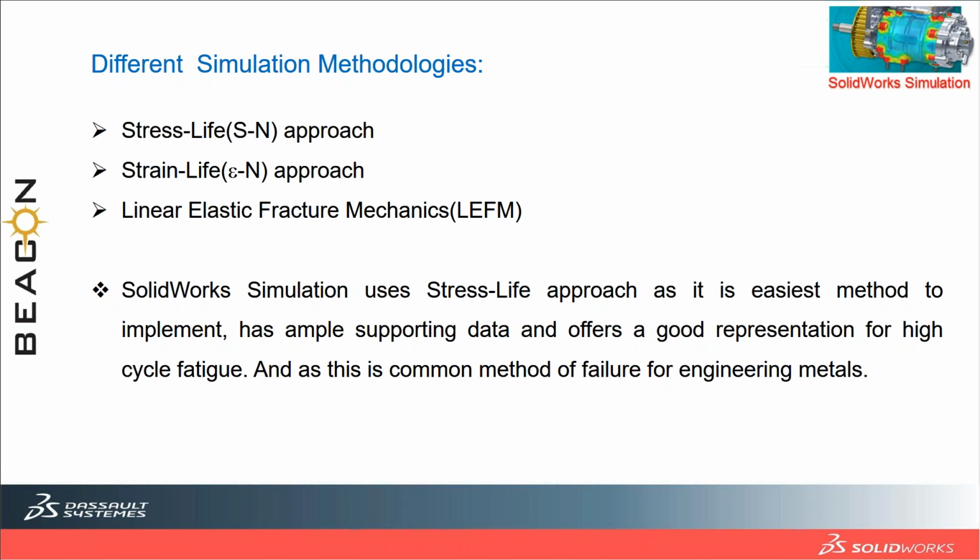So we have a strain life approach also available. In SolidWorks, our approach is S-N only. What is the strain life? I'm just giving a brief overview. It considers the plastic strain effects happening around the crack tip, where you want to measure the strain during testing. If you want to perform this type of fatigue analysis, you require a strain life approach. And the linear elastic fracture mechanics assumes that some crack is already there, and it considers both the crack creation and propagation.